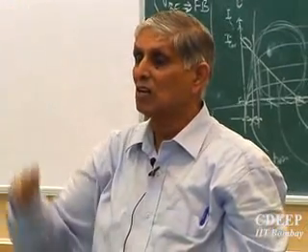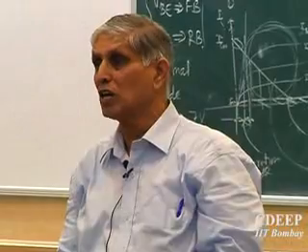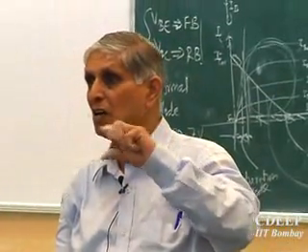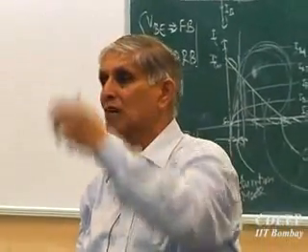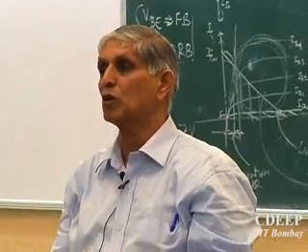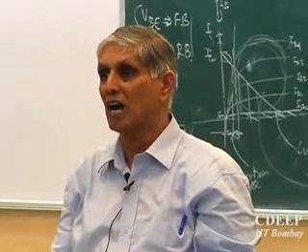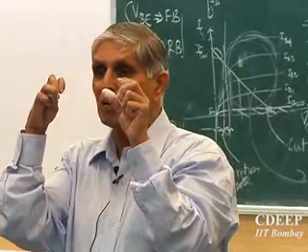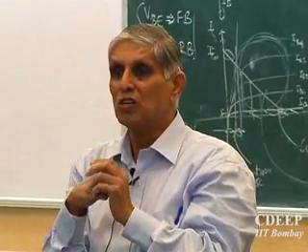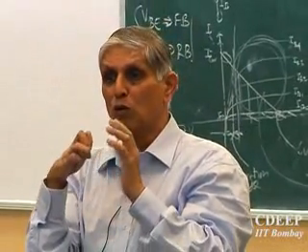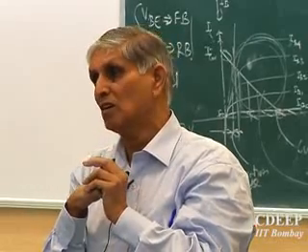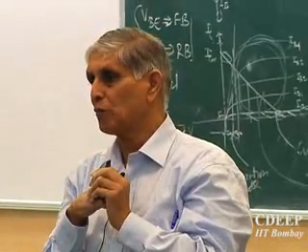So I am seeing amplification, and the input signal will get amplified by beta times. Because the collector current will proportionately rise, the device will still remain in active mode. This relationship can therefore only hold if the device remains in active or normal mode of operation.